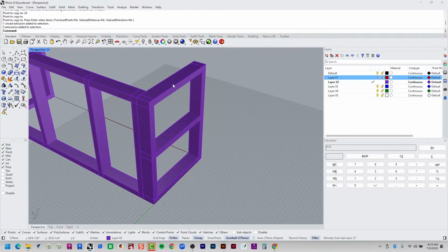In FrameCAD, it's called a bottom plate. The verticals are called sticks in FrameCAD, but in construction, we call them studs. But FrameCAD-wise, New Zealand-wise, you got sticks and noggins and bottom plates and top plates.